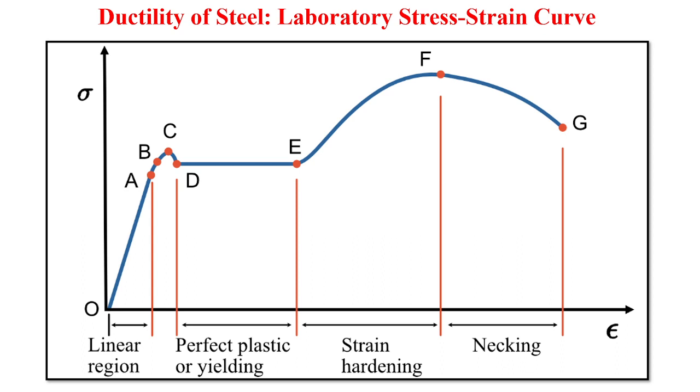Now, the metal of the rolled steel beams doesn't usually exhibit any upper yield point, and therefore the theory of plastic bending is based on the assumption of a steel without upper yield point. The strain up to point E in this graph is approximately 1.5%.